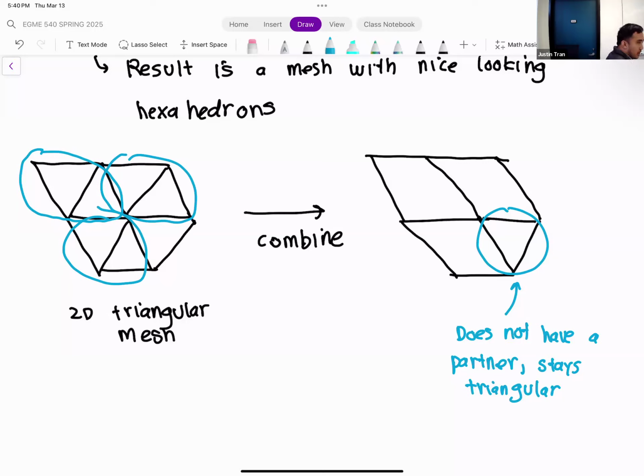But for a hexahedron, a node can belong to lots of different types of elements, and there are a lot of different connections to make. So this is a very clever way to do it: start with a tetrahedron mesh, where the theory is very well matured and developed for creating generic tetrahedron meshes, and then combine elements in a smart way to create hexahedrons, which, as we know, have very nice properties for your solution.